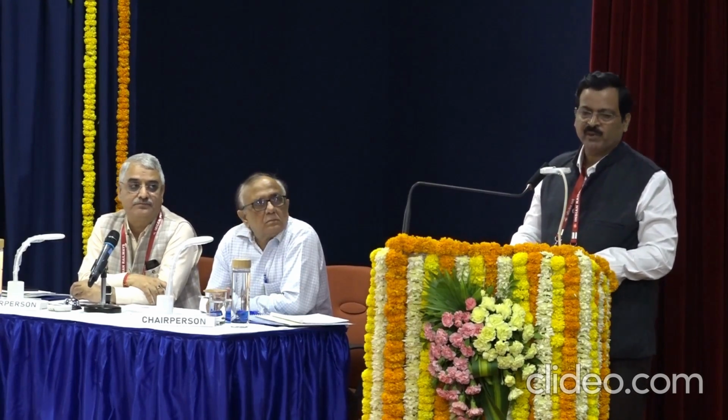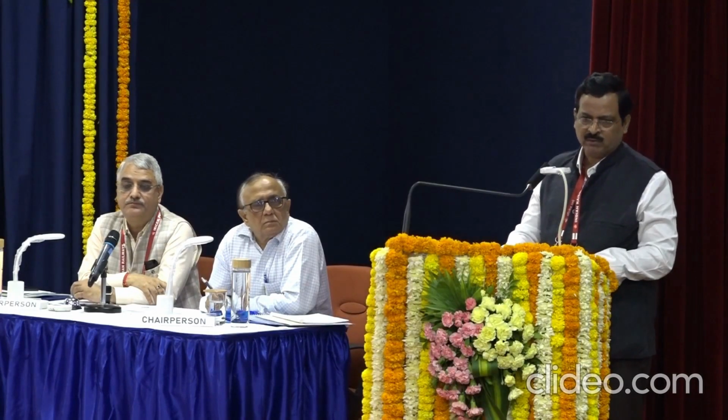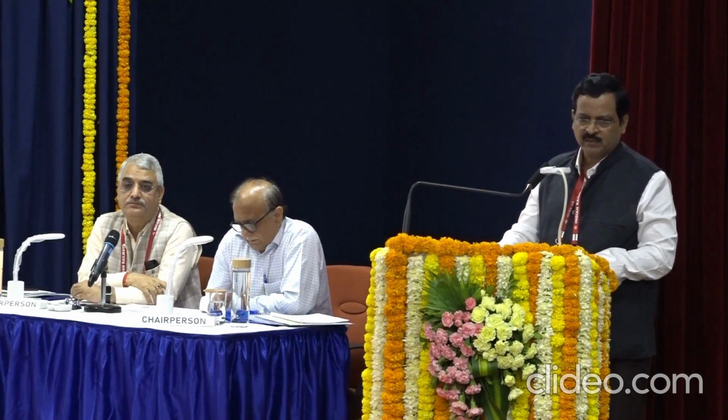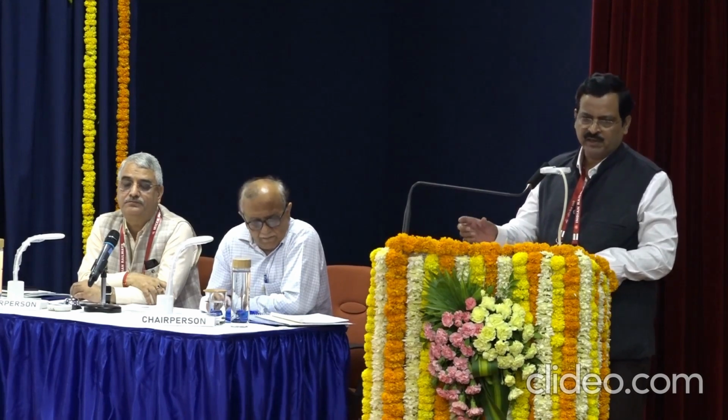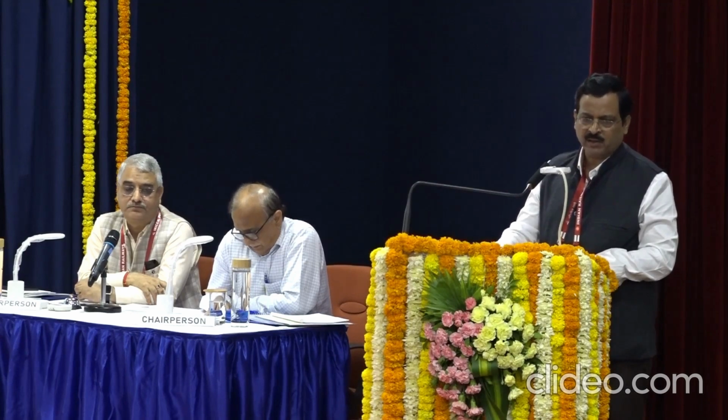When we do the modeling, after that we start the simulation. First we test the loads under static condition. There is no speed. We find the stresses. The result comes in the form of stresses in the member. Now we start running the loads. At all speeds, stresses will increase. So the increase in the stress is due to CDA. Suppose first under static condition the stress is 100. Now the stress is increased to 150. So 50 part is due to CDA. So in this condition CDA is 0.5. So this way it is determined.